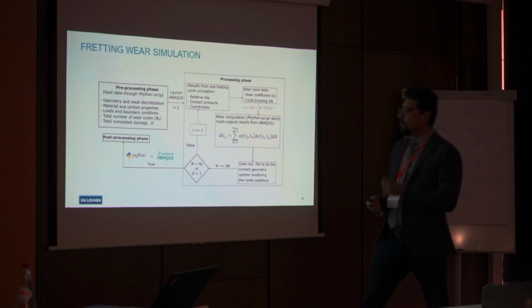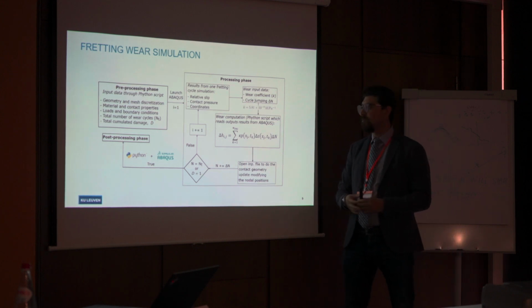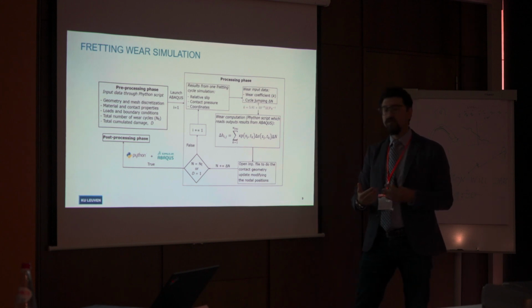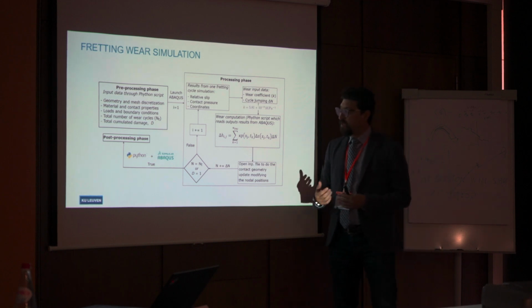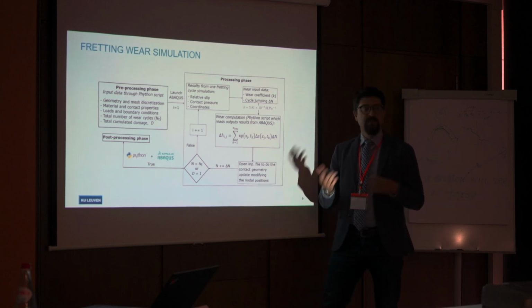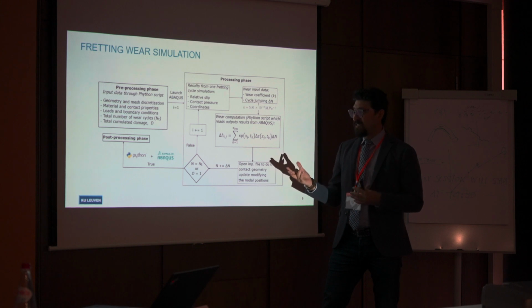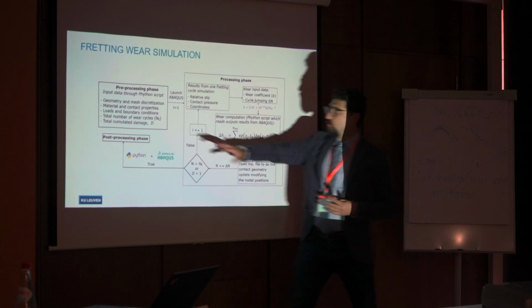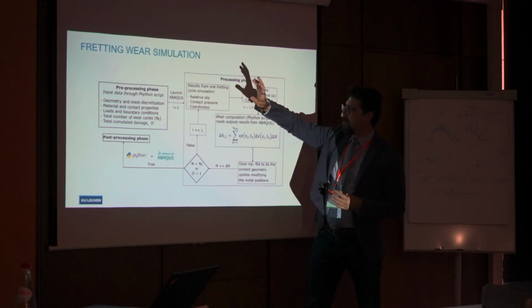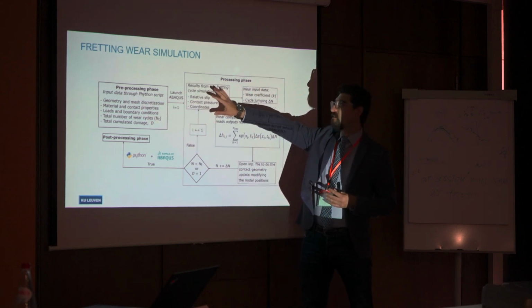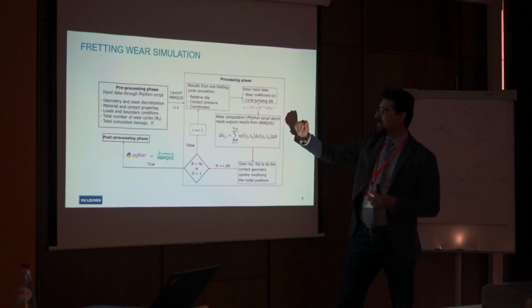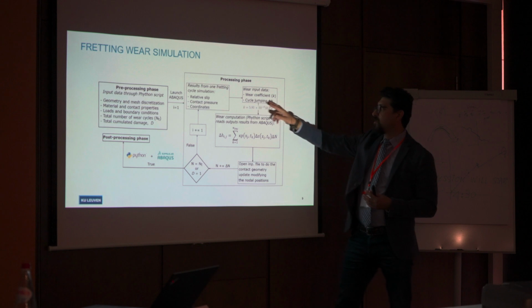Next, we used the Archard model, and we tried to simulate the wear process both in the fretting pad and also on the specimen, actually at the contact interface. There are two possibilities in Abaqus. You can use a subroutine, but we used in this case Python scripting to do all the things in a single mesh. So we create the model with Python, and then we try to analyze the data at the contact interface, and then we use the wear coefficient, as you can see here. We took it from literature, and some jumping cycles.